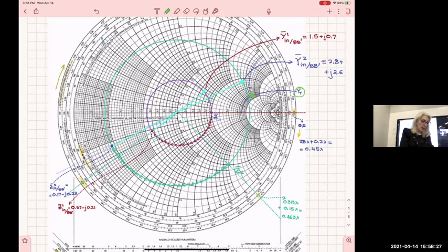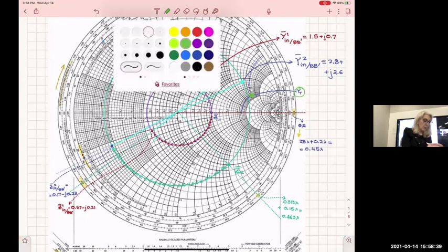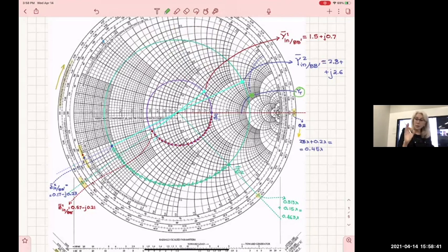From there, you can find ZT diagonally. The circle is very close to the green one, the big one, you see? They're not going to be very different. So you're going to come down here. If you draw the big circle, I would like you to do it. Draw the circle that goes through the YT, the transmission line circle. Find ZT from YT, and then from there, move by 0.1 to find the input impedance.